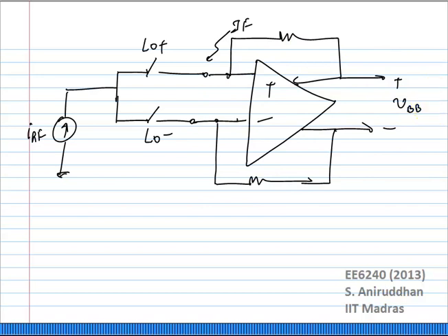Okay. So this gives you a differential virtual node, and therefore for the differential current flowing in, it looks like a very low impedance, and this current actually flows through these impedances to give you a voltage. You can embed some filtering inside it if you want, and so on. This is the preferred way of working with these current mode passive mixers.